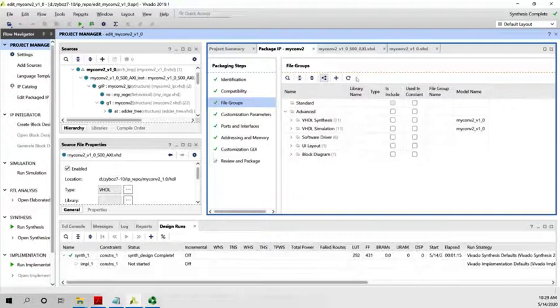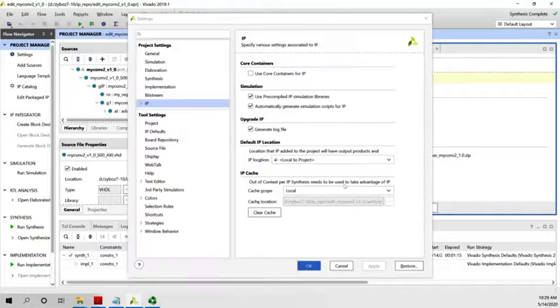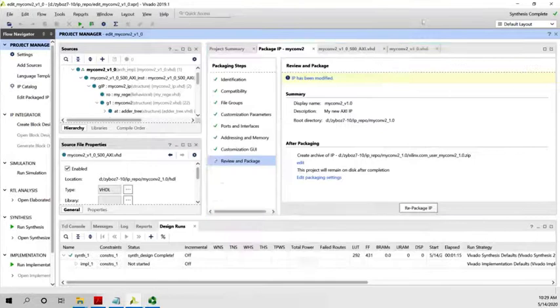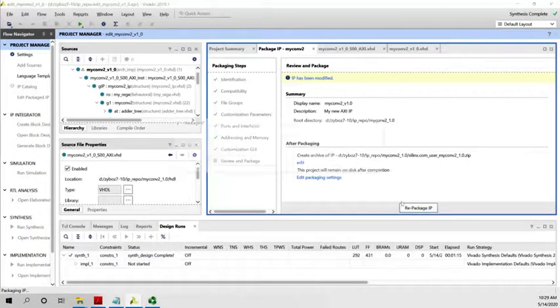It's like we have to tell Vivado that we actually did that. And then we just say we package our IP. Okay, this step, by the way, is very important because this is a step where the IP is going to be placed into the library of Vivado, so next time you can just drag it and drop it onto any new project that you like, by the way. Okay.